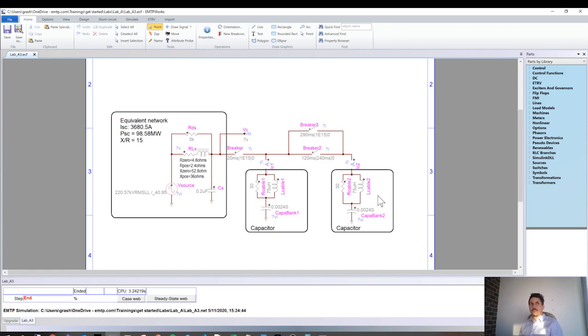Well, when you open the circuit breaker, you will have an arc forming. The arc will extinguish at the zero crossing of the current, so a circuit breaker always cuts current at zero crossing. And for a capacitor bank, the zero crossing of the current is the peak of the voltage, because there is a 90-degree phase between voltage and current for a cap bank. And so anytime you disconnect a cap bank, you will have the peak voltage